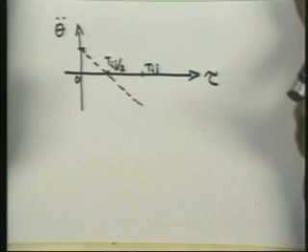So, given any two positions i and j with prescribed velocities, you will be able to determine the coefficients C0, C1, C2, C3 for the cubic spline curve fit for the individual joints' motion in this manner. Okay. Once you have got these coefficients, given any value of Tij and the values theta i, theta dot i, theta j, theta dot j, you will be able to compute this and actually generate the motion through the individual joints. Okay. So, this is feasible, but look at how it could be implemented in actual practice.